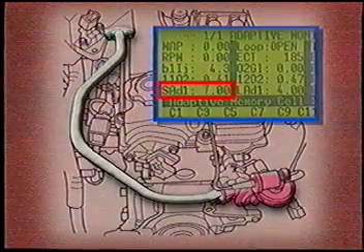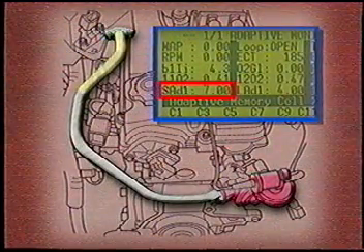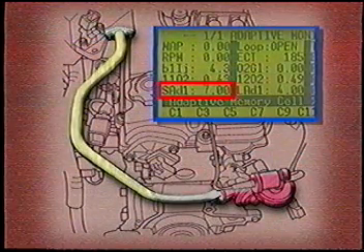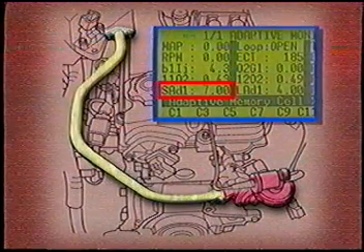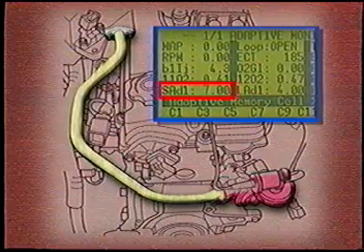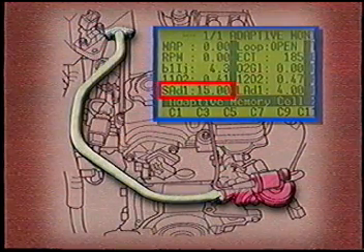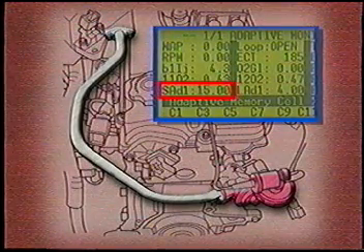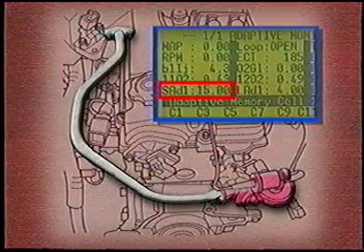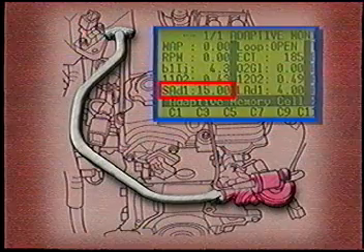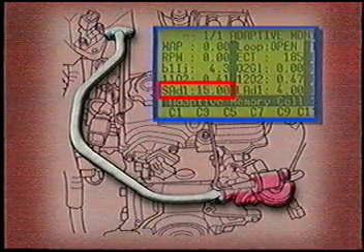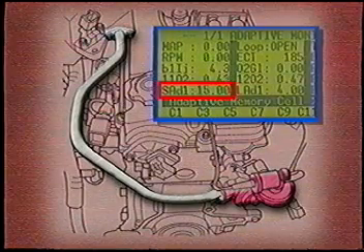When EGR is flowing, it displaces air in the combustion chamber, which lowers temperatures, thus reducing oxides of nitrogen. When the system is tested, the PCM turns off the EGR solenoid, which causes an increase of oxygen into the combustion chamber. The PCM then compensates by adding fuel. At this time, the EGR monitor looks for the increase of fuel to be above or below a certain level.